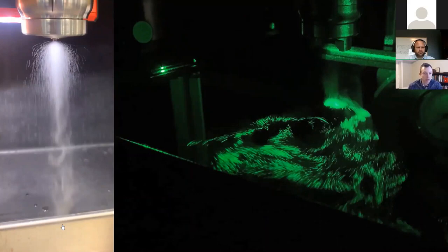And the spray down below, you can see how it looks like a fog almost. It's so small. And then on the right-hand side, you can see where that spray is going. You can see how susceptible these droplets are to any type of currents in the air that might be in a factory or in a process facility where you're going to use one of these nozzles. They're so small, they just move around, right? You can't really direct them towards the target, but by adding some shaping air and directing them towards that target, you can have a much more improved transfer efficiency to get them to the surface or through the process.